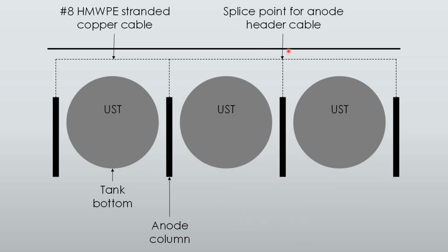You'll have all your anodes spliced together. Usually you'll have nicer systems that have individual leads brought up from the anodes, and they'll be brought to an independent junction box somewhere, and then they'll be hooked into a common bus bar. Then that bus bar will have one final lead that will hook up to the rectifier, but hooking them up in series like this is very common.